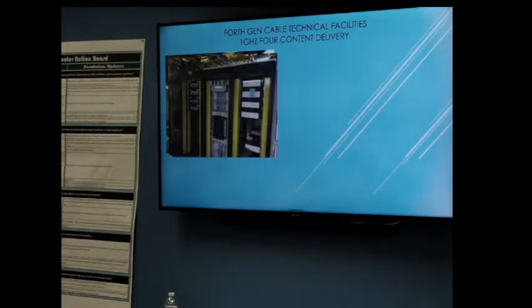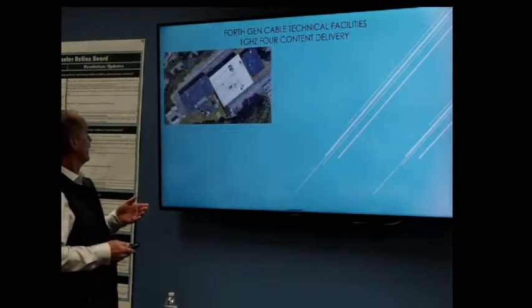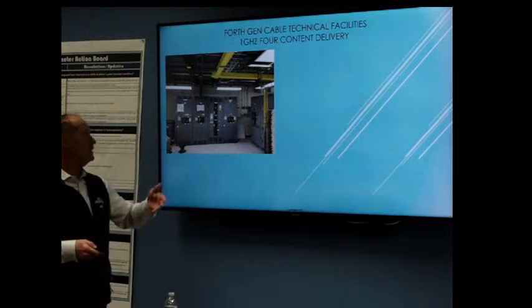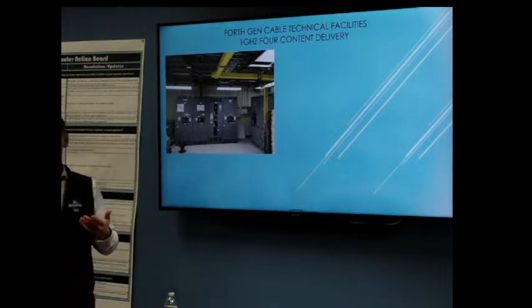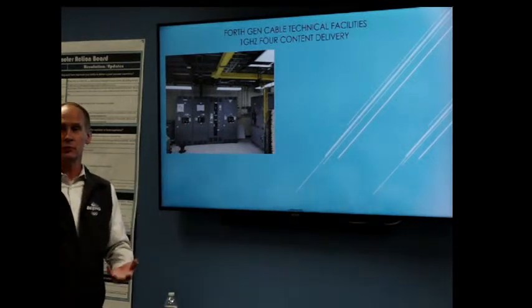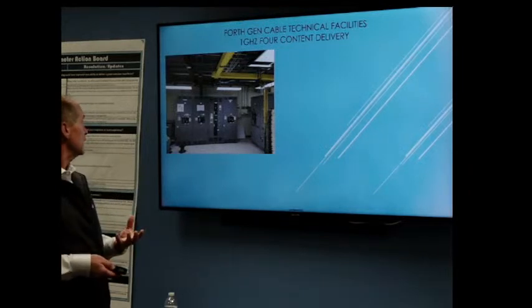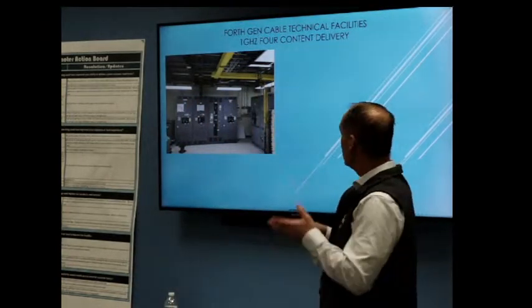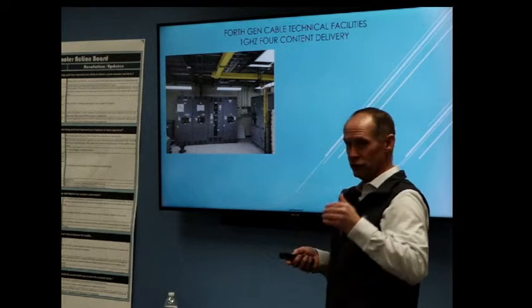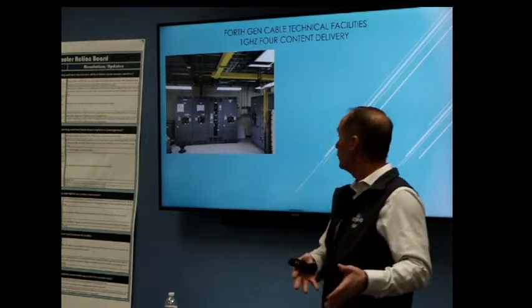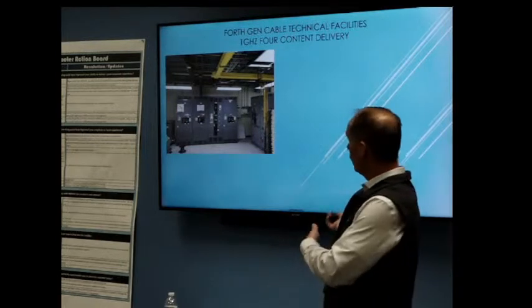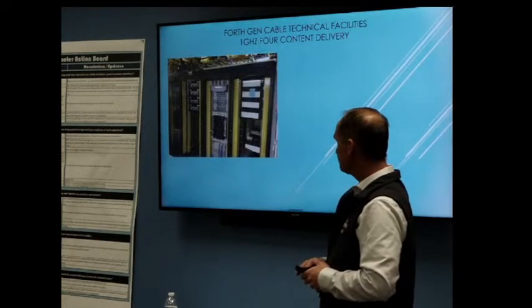You've got large industrial size switchgear. A lot of this industrial size switchgear is because of the kW and the amperage that's needed to support this much infrastructure, and broadband compute and processing really is the driver for a lot of this infrastructure. The amount of electrical distribution went from a small 200 amp single phase in the smallest of the buildings to a 1 megawatt distribution system.